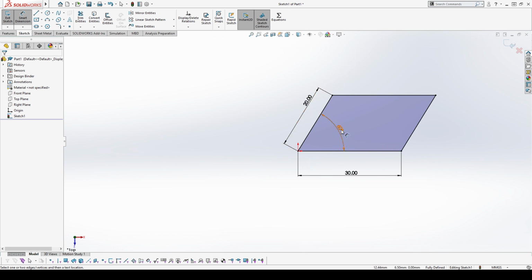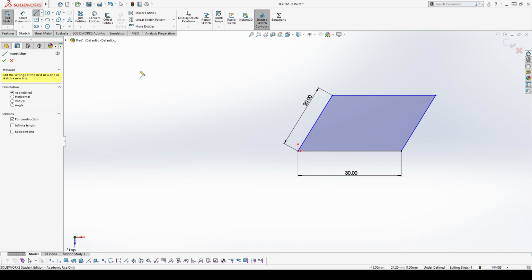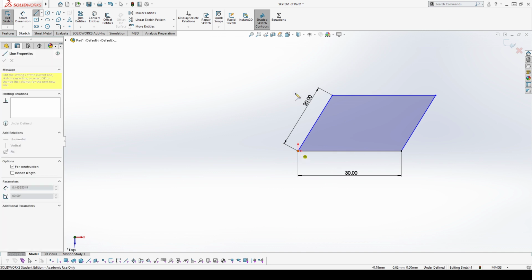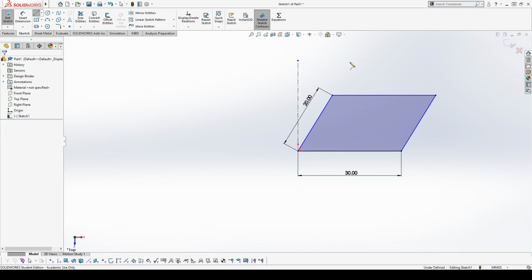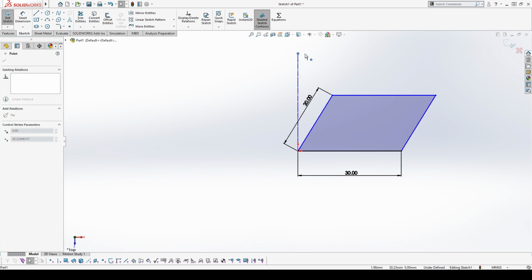So now, the question that I pose in my workshop is, well, what if I don't want to define the included angle? I actually want to figure out what this is from the vertical instead. So I'm going to go ahead and delete this dimension here. And then I'm going to draw in a vertical axis. If you remember what we talked about with lines, we have our center line, which basically just gives us a construction line. And it's arbitrary length, doesn't actually create any geometry.